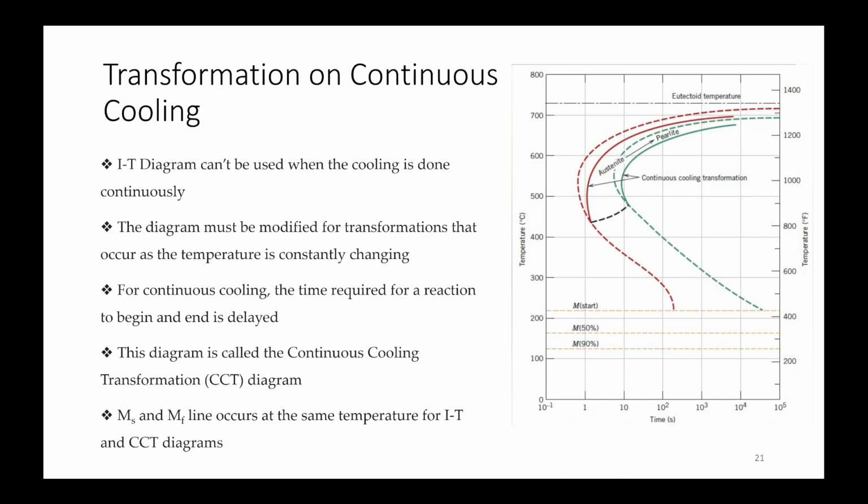Okay, so you will be drawing various cooling curves for different compositions. If you are drawing for a particular composition, you will see that when there is a phase change, there will be a particular slope. Then a change, then it can be constant. If you see that type of change, you will draw your transformation lines on that particular composition.